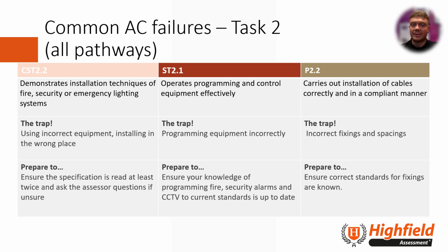P2.2 carries out installation of cables correctly and in a compliant manner. So the trap with this one is incorrect fixings and spacings. So, in order to prepare, ensure current standards for the fixings are known, so you're aware of exactly what you need to do during those assessments.